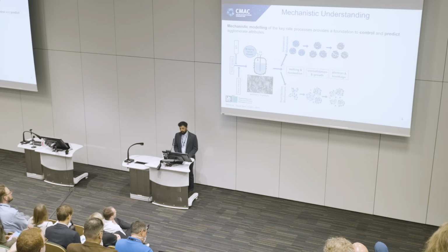So for the first mechanism, we have the immersion mechanism. Well, I should probably say before then that these mechanisms are essentially controlled through the relative size ratio between your bridging liquid droplets, where you add your immiscible binder liquid to the suspension of primary crystals. In the case when we have a smaller bridging liquid droplet size compared to your crystals, a distribution mechanism takes place where we have the coating of crystals around the droplets. On the other hand, in the immersion mechanism, if you have a larger bridging liquid droplet size being added to your suspension of crystals, which are smaller in size, we see the gradual encapsulation of crystals within the bridging liquid droplets, forming, again, these really nice, dense spherical agglomerates. In terms of preference, we tend to work with the immersion mechanism, which has been our focus for the past couple of years.